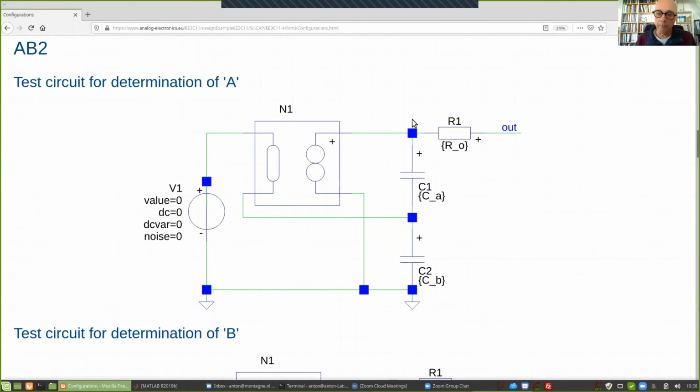So here we have a voltage attenuator. We compare it with the input. So this is basically a passive feedback voltage amplifier, and we created the output impedance by means of a brute force technique, just placing 50 ohm in series.